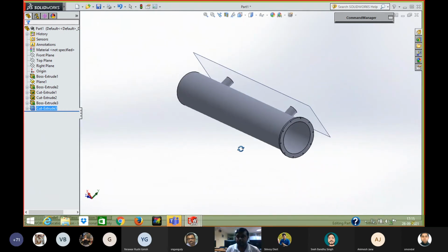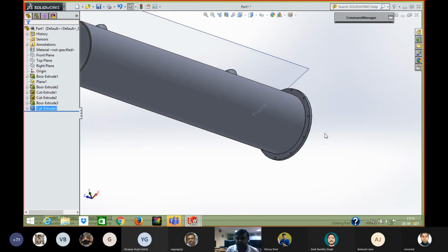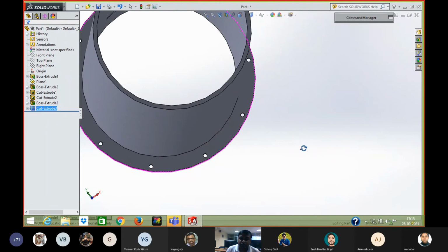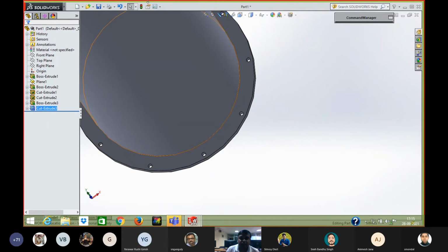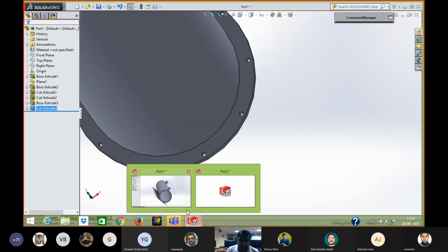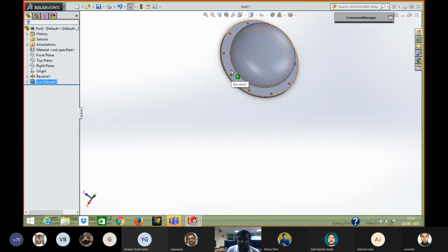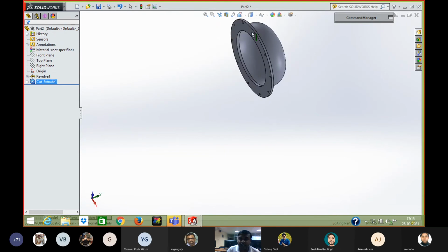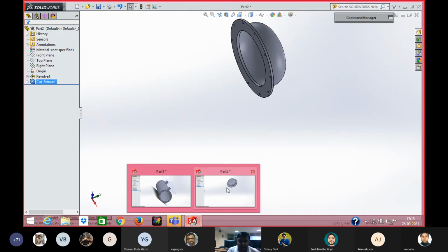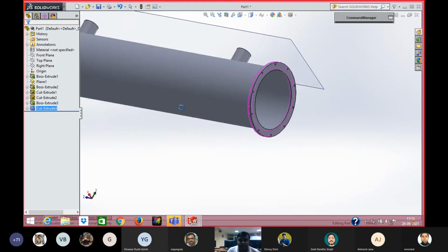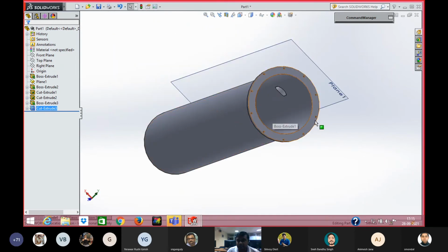Now see, this is the outer portion of the shells. You can insert the bolts with this section to the head of this shell, these portions. You can assemble it by using the bolt and nuts, isn't it? And in between this head and this shell, you can use a small gasket according to the inner diameter of these shells, isn't it?